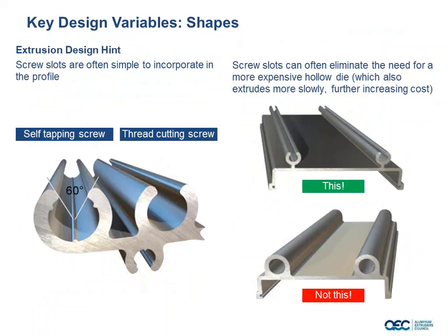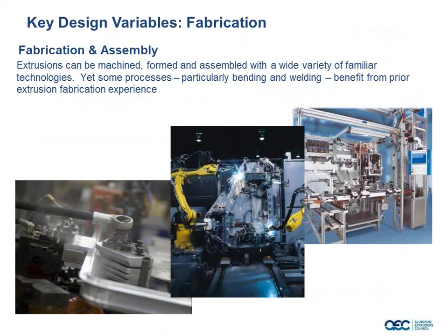Many times we see customers thinking that they need to drill and tap the holes. And here is a great opportunity for self-tapping screws to be used, and where you can eliminate the entire machining process, hence the cost as well as the time to market to get that tooled up.